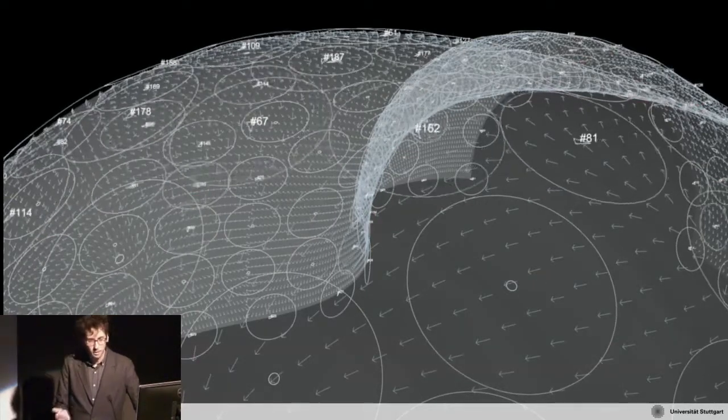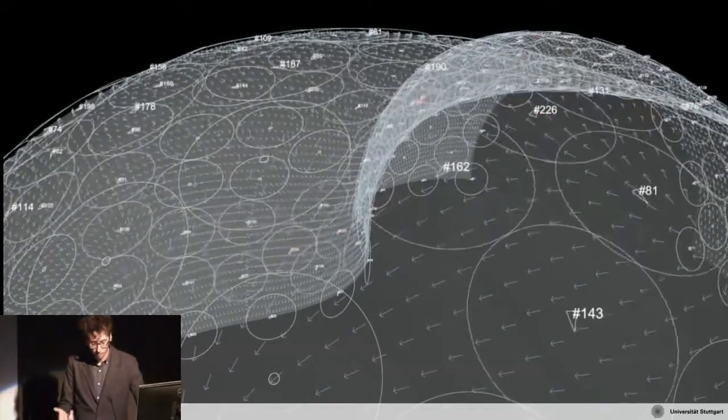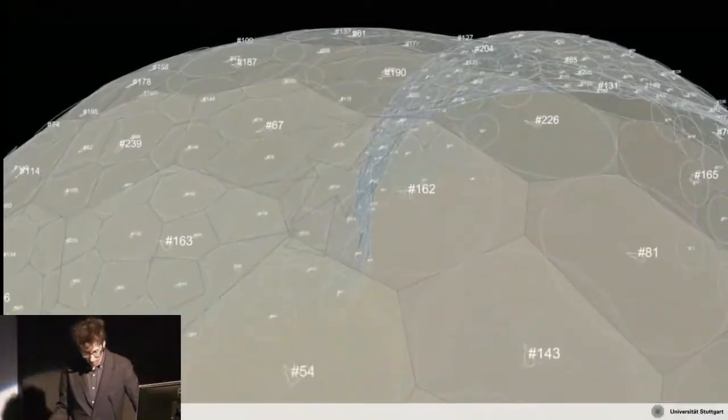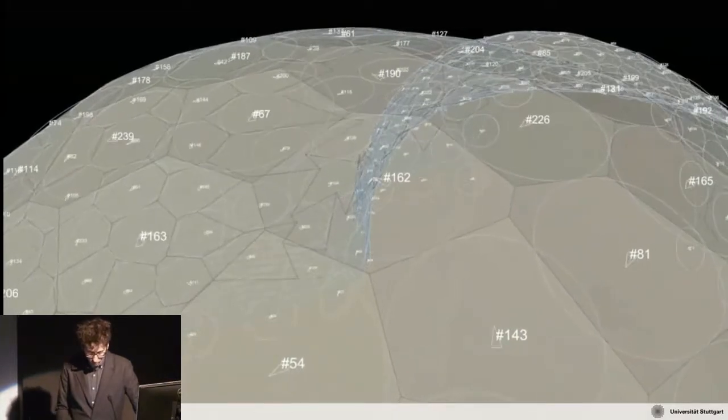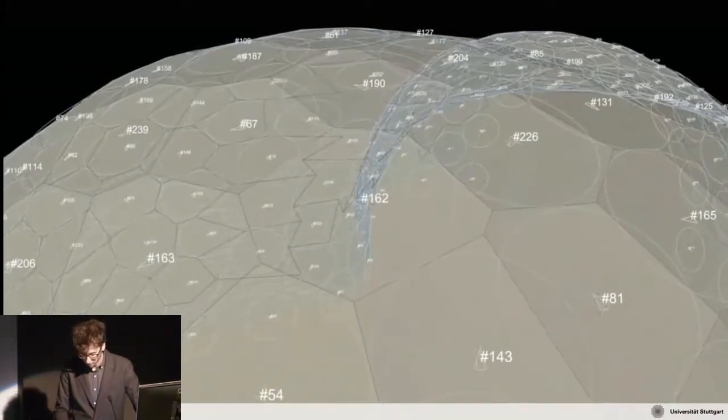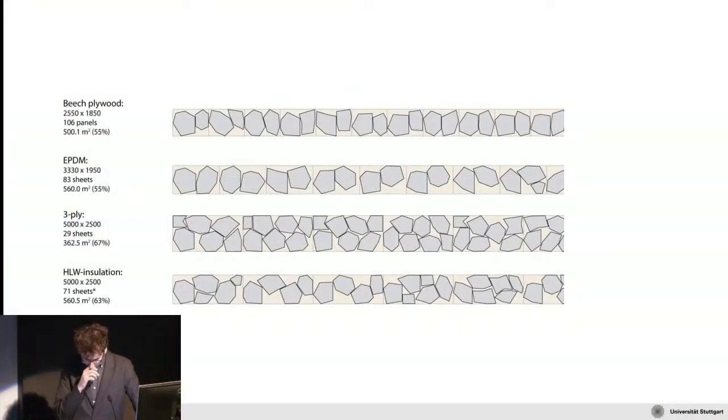For example, the plate shouldn't be too big, it shouldn't be too small, it should be fabricable. So there is information about the maximum and minimum size of the plate. There's information about what the stock material is that we're working with. So how can we later nest them, and that's what you see here, into the stock material to be also material efficient in this case.